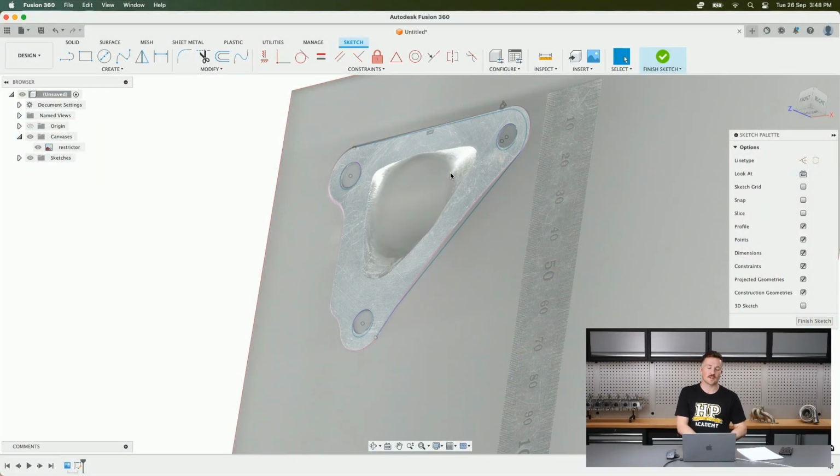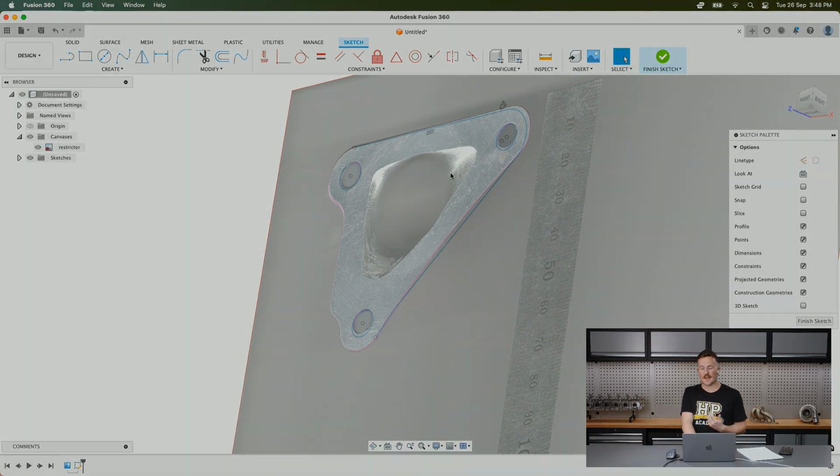Sketch around the part, and then we can design and copy that flange exactly from the photo, with a bit more care than this, obviously. But that is a really good way of reverse engineering basically from a 2D image, and we find that using a flatbed office scanner is a really good way of doing that. Obviously, you've got to be very careful with the glass on it, but that gives you a nice image with no distortion in it like you might get from a wide angle lens on a camera.